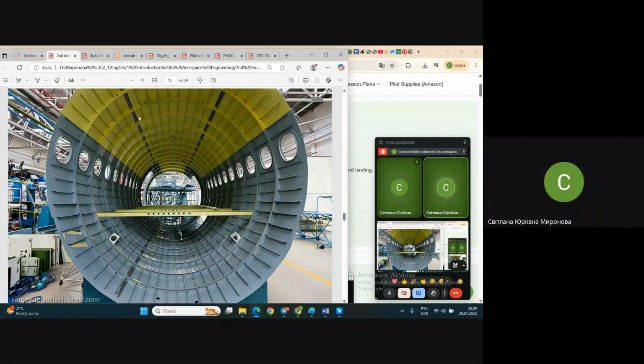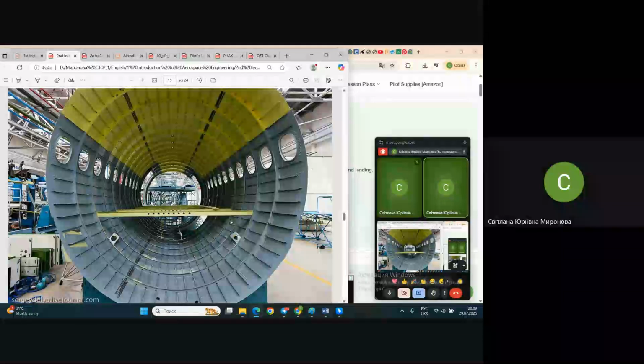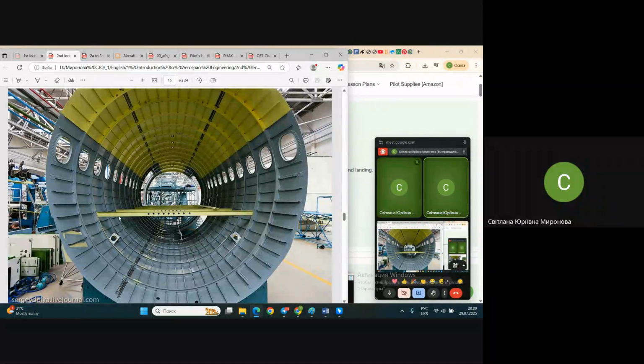It has a cylindrical outer skin shape, and longitudinal elements and so-called transversal elements, which are responsible for the shape of this fuselage. Now it's quite clear it has some additional elements. What right now we need, for instance, is to place here the floor. And these supportive elements also in transversal direction, so-called beams, are placed here.